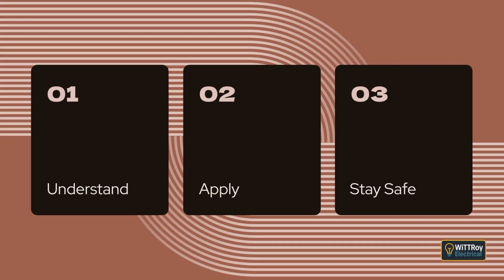Clause 3.9.9.1 General. Where wiring systems pass through building elements, precautions must be taken to limit the spread of fire. Where equipment contains flammable liquid, measures must be taken to prevent burning liquid from escaping and spreading fire. Where building dimensions increase fire spread risk, precautions must be used so wiring does not contribute to fire propagation.